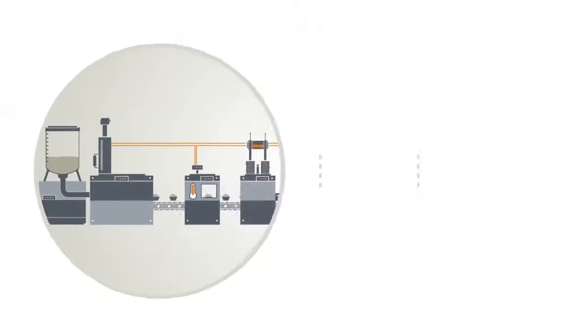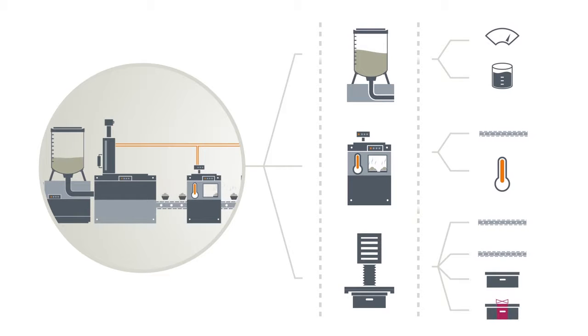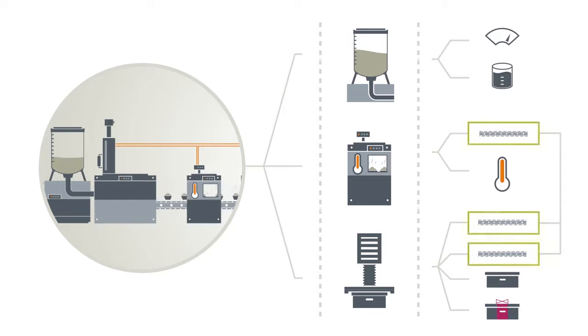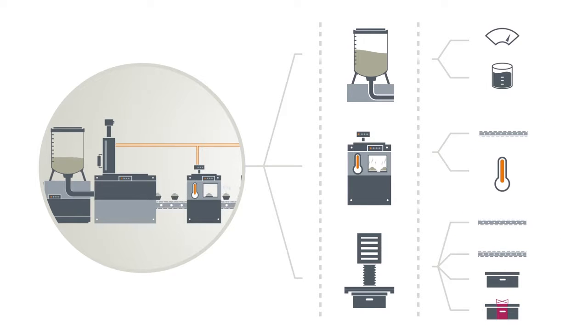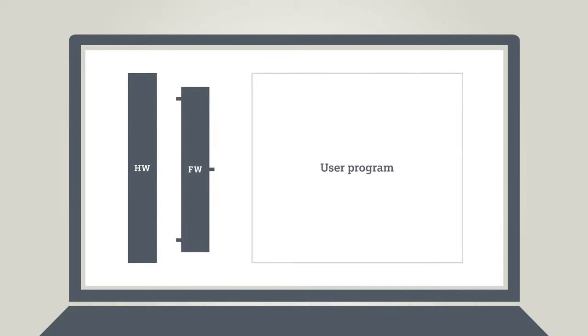An automation programmer might further subdivide each of these subsystems into individual technical units, such as mixers, conveyors, and packaging. Even these can often be subdivided again into identifiable functional units that can be jointly used by multiple technical units, let's say multiple conveyor belts. This type of structuring forms the basis for easy solutions for complex tasks. And that is exactly where the TIA portal supports you with its programming and block concept.